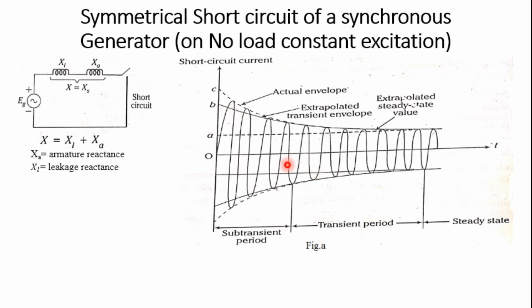This figure shows the trace of the armature current when neglecting the DC offset current. This current will be similar in all three phases except for a phase angle difference of 120° electrical. So this is what we can see.